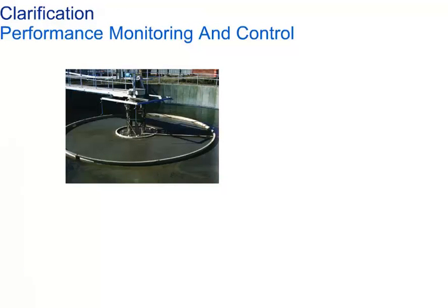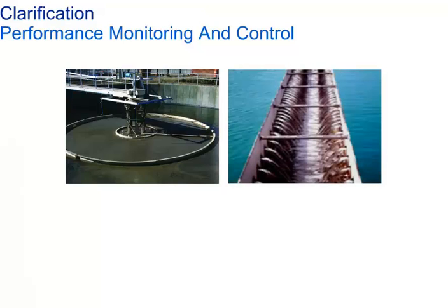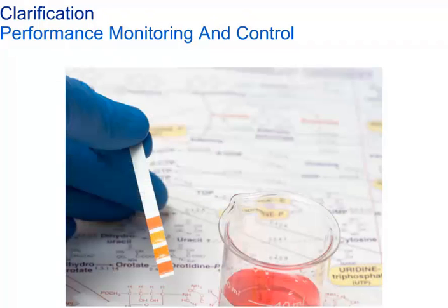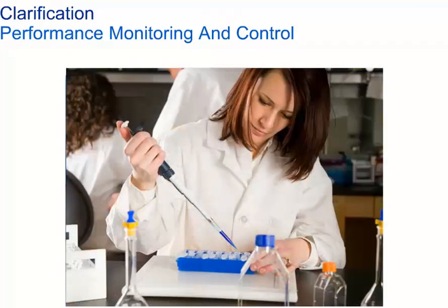After coagulation, flocculation, or sedimentation, the water is sent to a clarifier for further treatment and conditioning. Tight controls are required as the water nears the final disinfection area. In the clarifier, we must measure flow to accurately establish chemical feed rates, wash water rates, and unit loadings. Monitor mixing and chemical feed systems to ensure proper dosage control. Monitor pH for optimum conditions. Quality tests are normally required almost once in every shift.